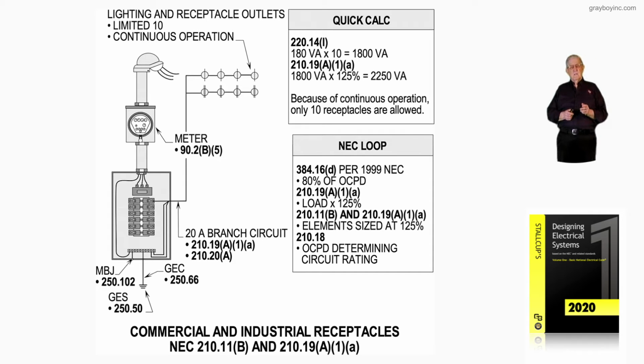Say that you increase the ungrounded conductors to number 10 for voltage drop. With the number 10 conductors at 30 amps, say, or maybe even at 35 amps, or maybe the 40 amps, that is used for derating purposes and so forth.